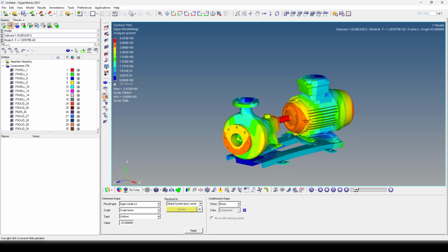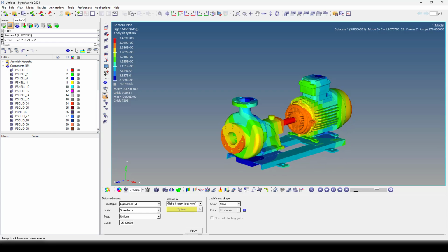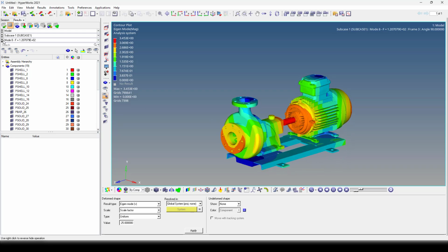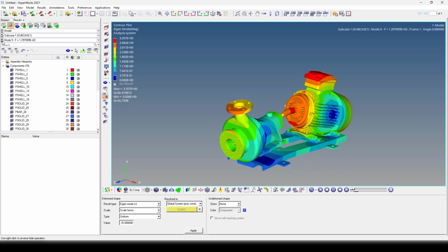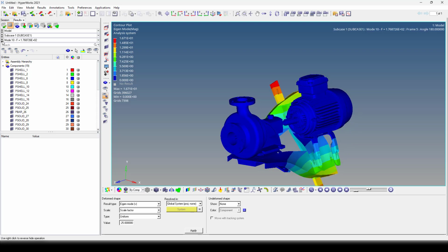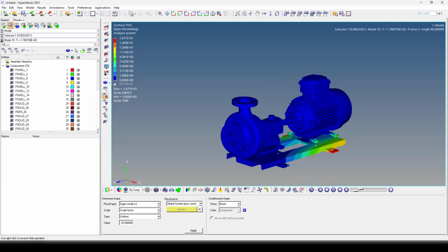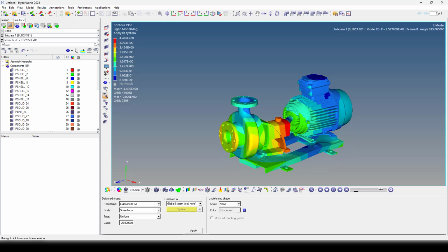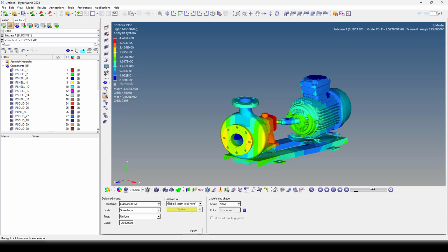This is the bending mode, the eighth one. You could see the stiff model, and you could see the plates are vibrating much, at the bottom, the 5 mm thin plate. Similarly, if you go to the next, you could see again the plate is vibrating much. This is again the torsional, again the bending. After 10 or 12, these are all the local modes.